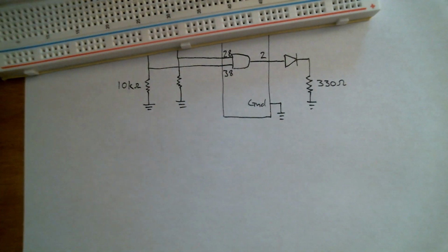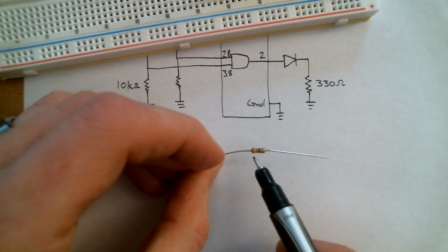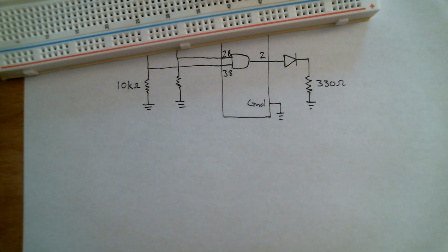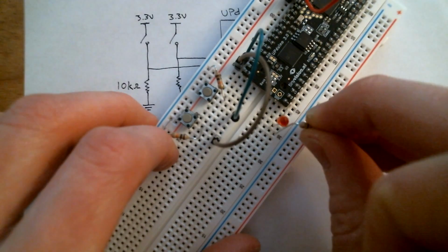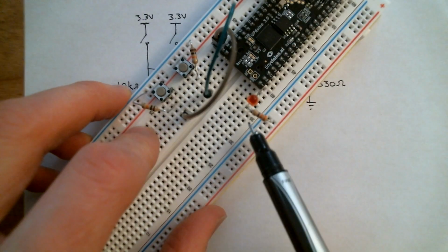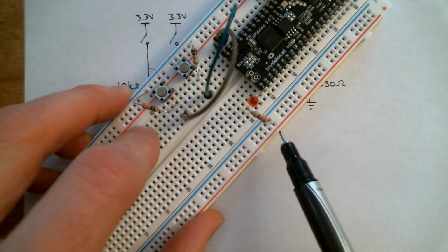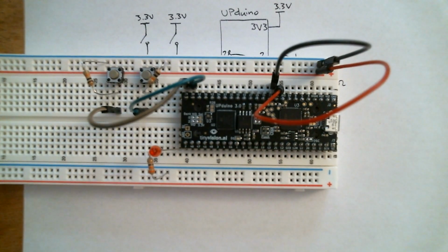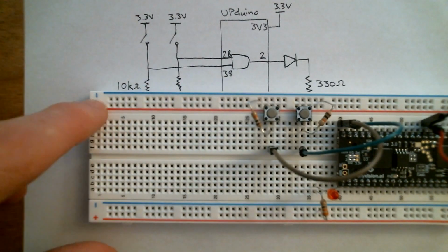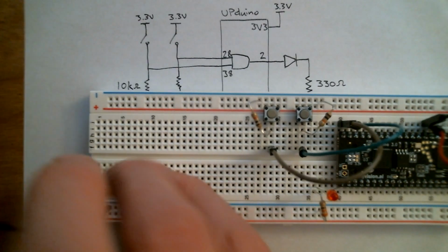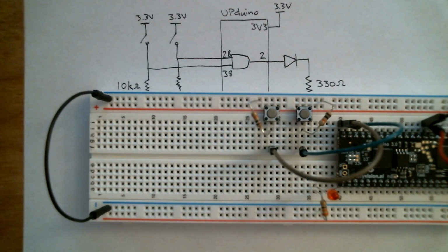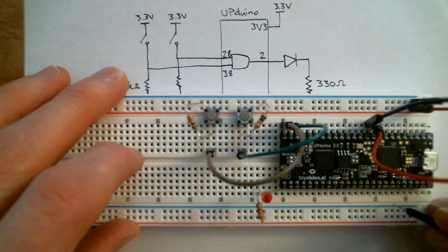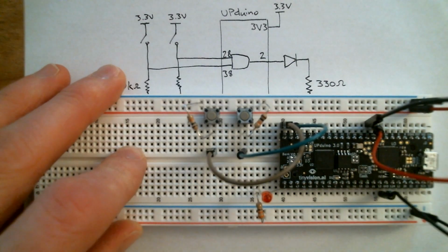And then finally we need the 330 ohm resistor. Again, it's orange, orange, brown. We can bend that one over and connect it in that same column and then to ground here. But this ground rail we haven't connected to anything yet. So finally we need to connect the ground rail to ground. We could either connect this ground rail over here like this, or we could use one of these other ground pins, so the ground pin here, and connect that on that side.